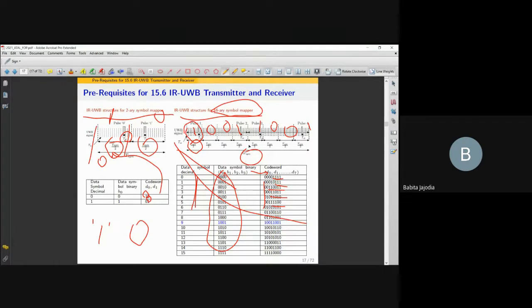There the role of the transmitter comes up. The transmitter will have a pulse generator, and it will allow the pulse generator to generate the pulse only at this window. It's somewhat sort of gating: you are making it enabled only for this time and off for the other time. For example, it has 16 slots here.